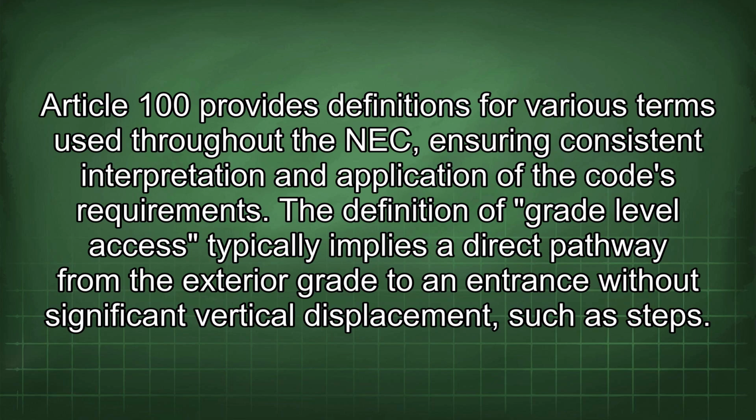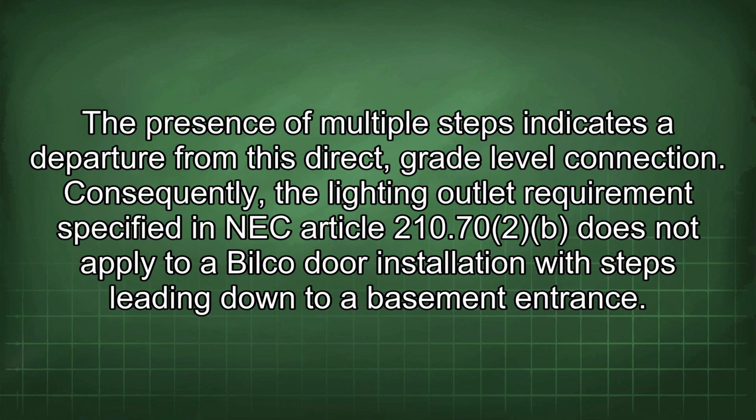The definition of grade-level access typically implies a direct pathway from the exterior grade to an entrance without significant vertical displacement, such as steps. The presence of multiple steps indicates a departure from this direct, grade-level connection. Consequently, the lighting outlet requirement specified in NEC Article 210.70 does not apply to a Bilco door installation with steps leading down to a basement entrance.